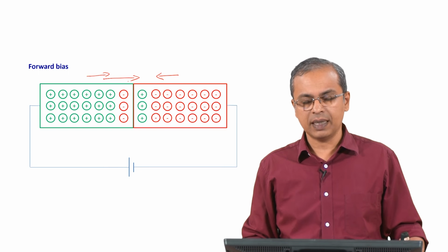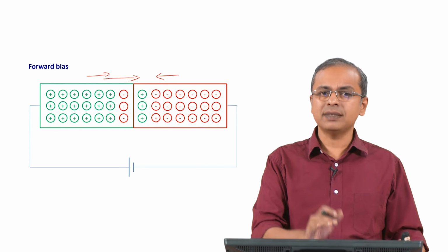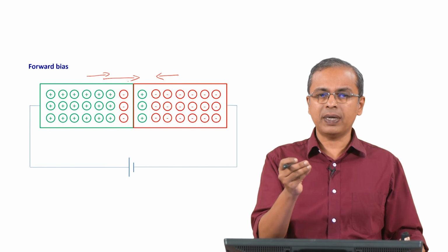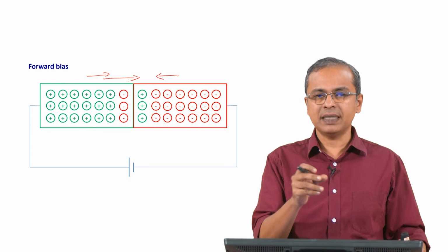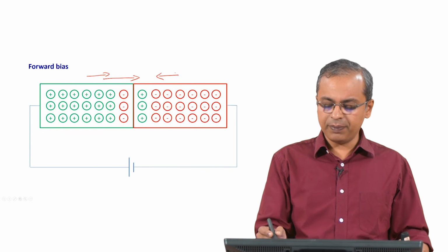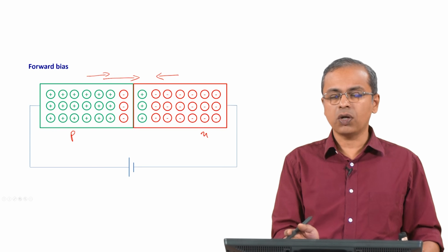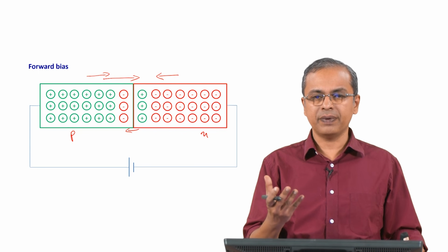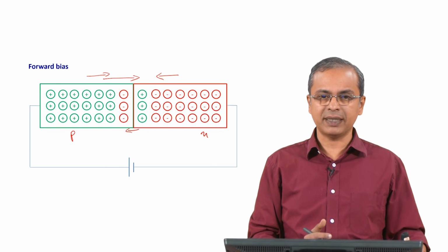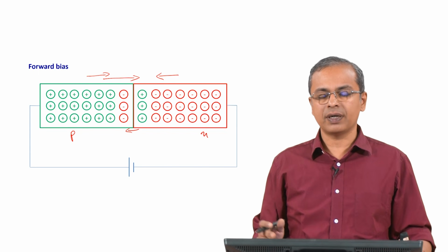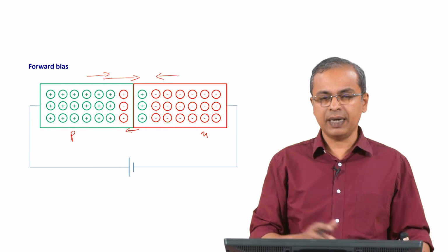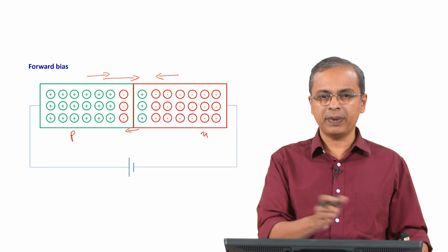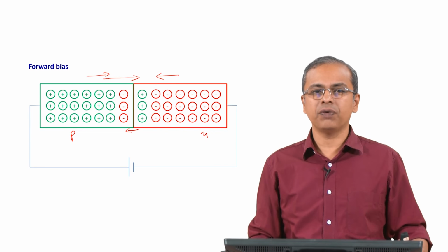and they are getting consumed by the holes coming from the other side, and hole essentially means the sample is charge neutral, but the bonds can actually accept one additional electron, right. So, that is what we mean by saying that there is a hole there, and so this electron that is coming from the n side, as it crosses the boundary and goes into the p side, it is actually going into that location where that one additional bonding electron was not available. So, it is readily accepting that electron. So, the electrons are actually steadily flowing from your right to left, and as it sits in that location, one more hole arrives, one more electron arrives, and it keeps occupying locations, and therefore, you can think of it as a current that is flowing.